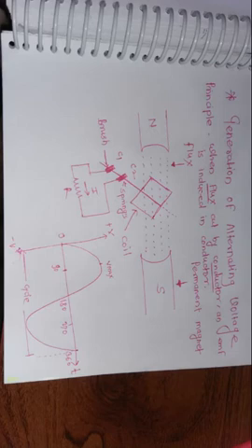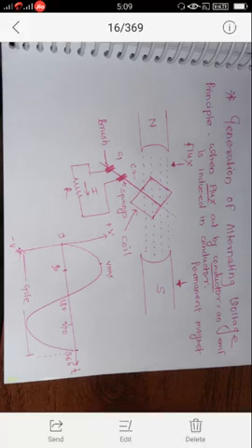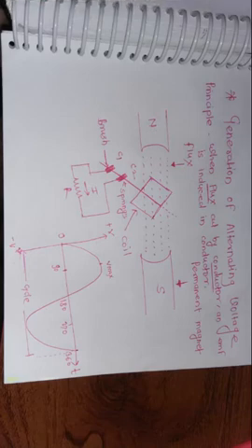Now again when we rotate this coil, the amount of flux cut gets reduced, and when this coil is at an angle of 180 degree, then no amount of flux is cut by this coil, so no amount of EMF gets induced in the coil. That is, at 180 degree the magnitude of voltage induced in the coil is 0.